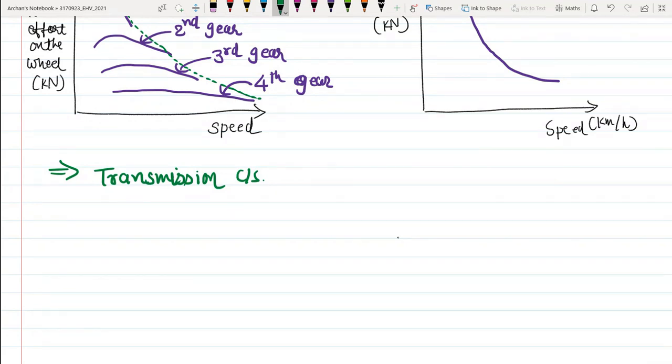We have already mentioned previously that a well-controlled electrical machine, such as the power plant of an electric vehicle, will not need a multi-gear transmission. But an internal combustion engine must have a multi-gear or continuously varying transmission to multiply its torque at low speeds. The term transmission here includes all those systems which are employed for transmitting engine power to the drive wheels. For automobile applications, there are usually two basic types of transmission. We know one is the manual gear transmission and another one is hydrodynamic transmission.